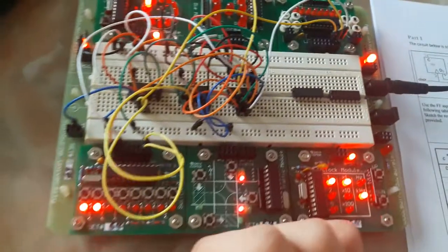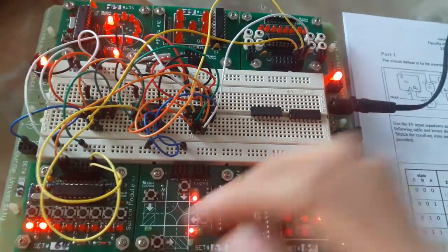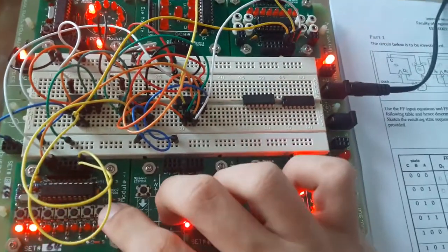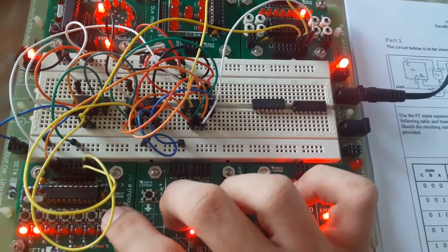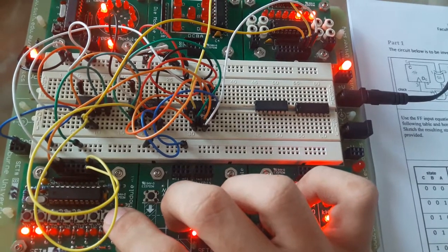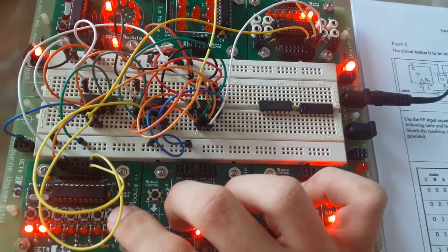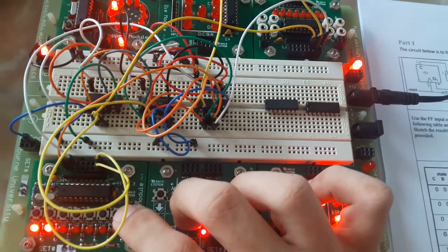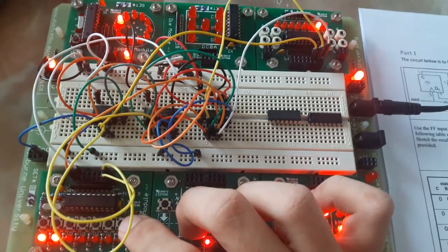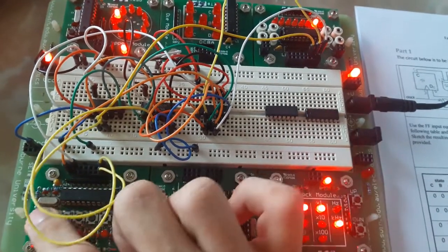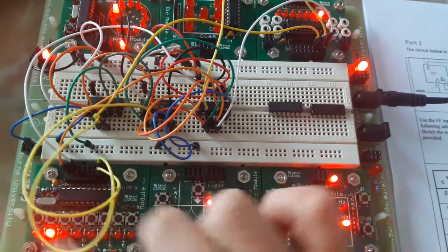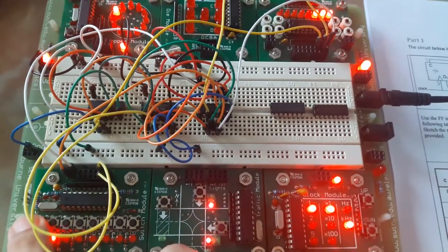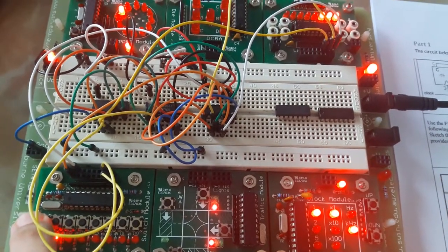Then we are going to test the result. So, firstly, the output will be 000, then the next states will be 010, 101, 100, 110, 001, and back to 000. Then at 010, we test the output by setting KB to 0. Then we get 111 and set KB as 1 again.